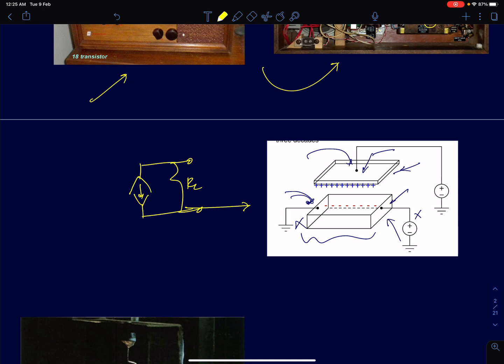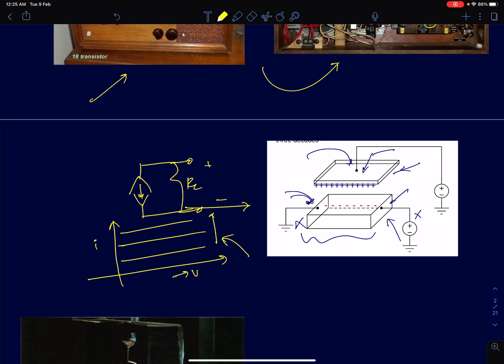So I had already discussed this in the first lectures. How should the IV characteristics of such a device look? We said that if any device exhibits an IV characteristic, which we will discuss at a later stage, wherein the current flowing in the device is independent of the output terminal voltage, but depends upon some external or third terminal, then it's a dependent current source. If you can build a device with these IV characteristics, then it can be used as an amplifier. That's what we discussed in the initial lectures, and we showed how a bipolar junction transistor can be used as an amplifier.